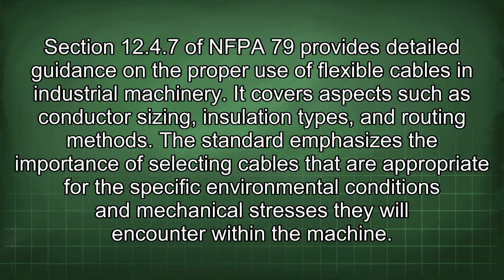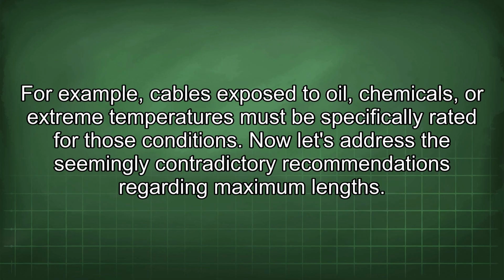The standard emphasizes the importance of selecting cables that are appropriate for the specific environmental conditions and mechanical stresses they will encounter within the machine. For example, cables exposed to oil, chemicals, or extreme temperatures must be specifically rated for those conditions.